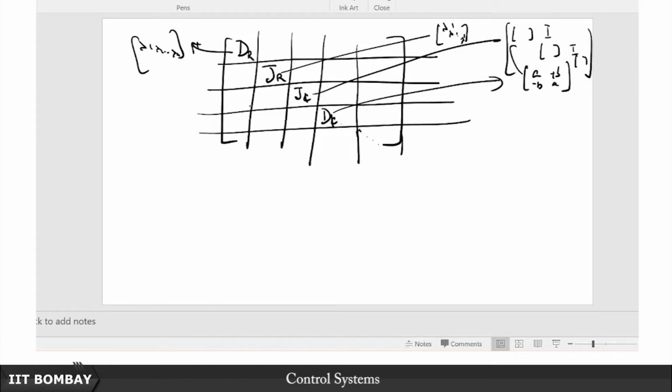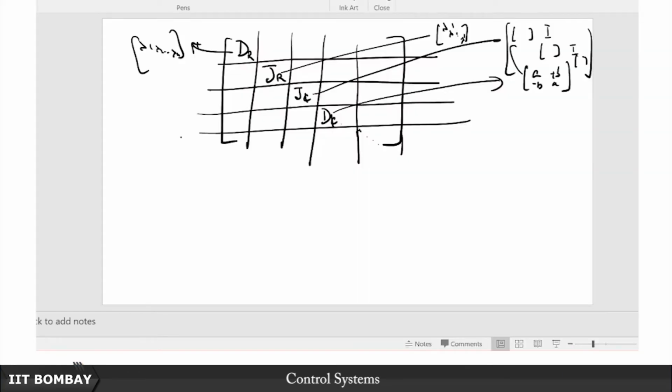Now we are not looking at the joint controllability and observability, but minimality. If we find that for minimality we need exactly the same conditions that we had established for joint controllability and observability in the previous lecture, then we are done. I repeat, from the same Jordan block, because we knew in terms of the Jordan block what the conditions for joint controllability and observability were. So if we can relate the same Jordan block realization with some equivalent condition for minimality, and in turn prove that those conditions are exactly the same as those necessary for joint controllability and observability, then we are done. So this is a typical A matrix when transformed into its Jordan block form.